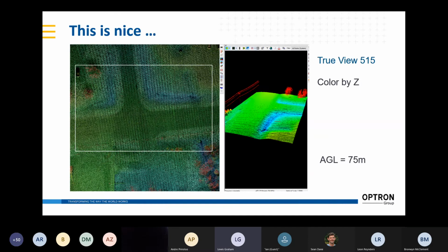So I would assume most people are familiar with LIDAR. It gives you direct 3D imaging of the ground using an active sensor, which is a laser scanner. So it's a big advantage over photogrammetry, in that only a single ray needs to hit the ground to get a ground point, whereas in photogrammetry, particularly multi-ray photogrammetry, I might need 5 images at separate locations that see the same point on the ground. And this is why you don't see vegetation penetration with photogrammetry alone.